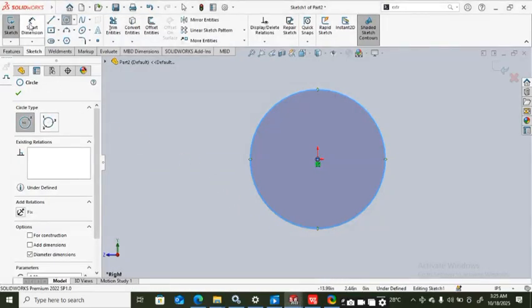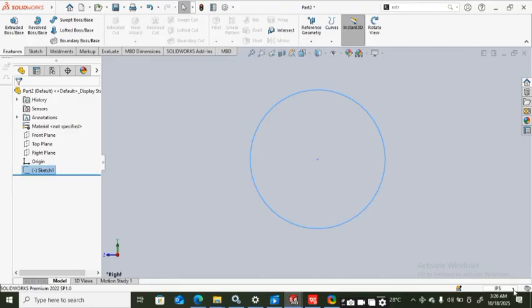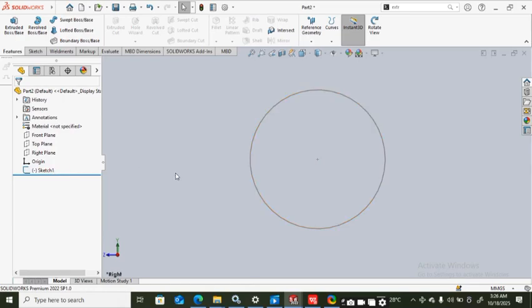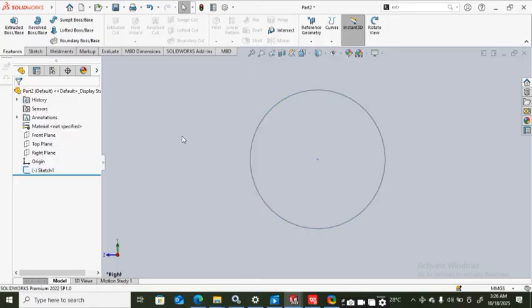Now I'm going to give my SolidWorks dimension. As I've discussed earlier, in SolidWorks we're working with millimeter. So I'm going to convert mine to millimeter so that we're going to flow in the same direction. Once we have done that, we're going to return back to my sketch. In this place, once you are done, you just take your arrow straight to this point, right click, and press edit sketch. Let me go back again. I actually went to this place to calibrate my SolidWorks into millimeter, gram, second.